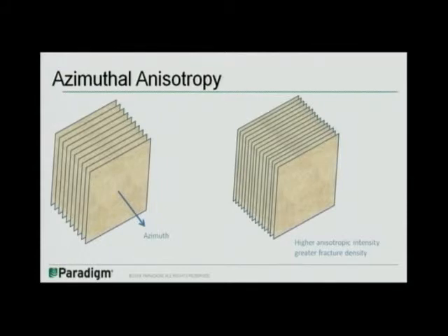You're right, this is just a conceptual model, and the reality is much more complex than that. But the theory is based on this theoretical model. If the subsurface doesn't fit this theoretical model, then of course you're not going to get a good estimation. The assumption is that the lateral change is not of small wavelengths. If the lateral change in the regimes between the fracture orientations is of a larger wavelength, then of course you can map it. But if every meter or so you have something else, then the seismic data will probably see it as homogeneous.